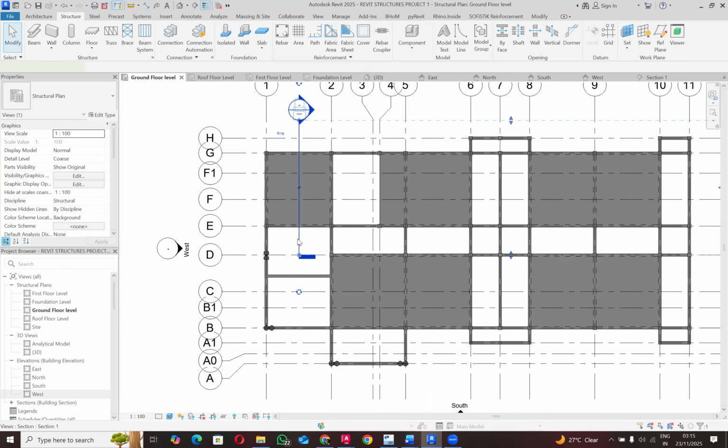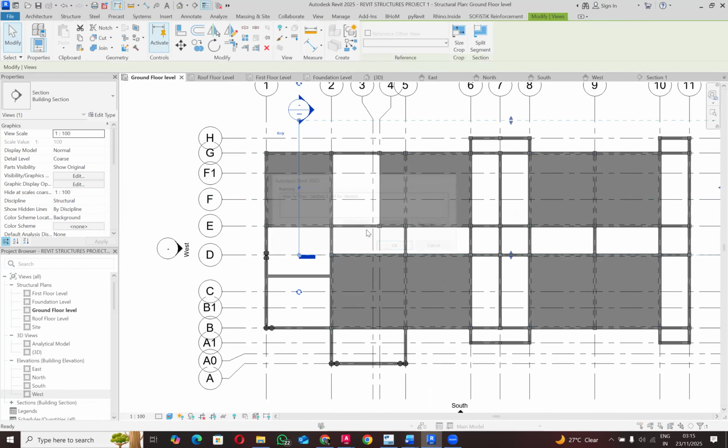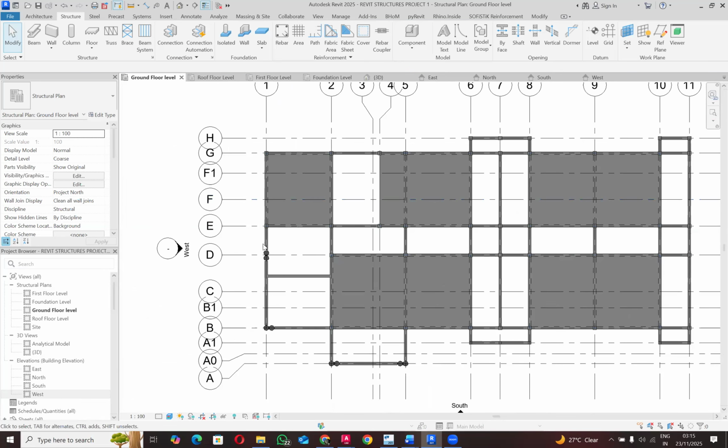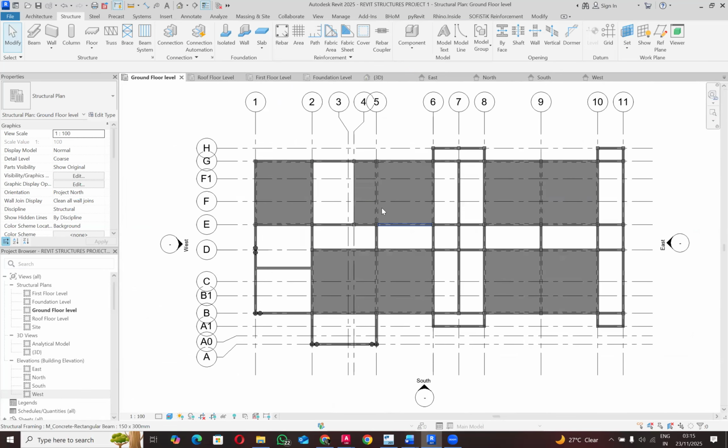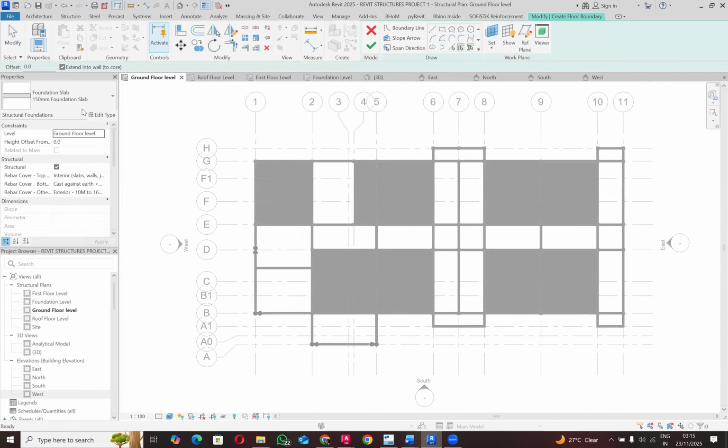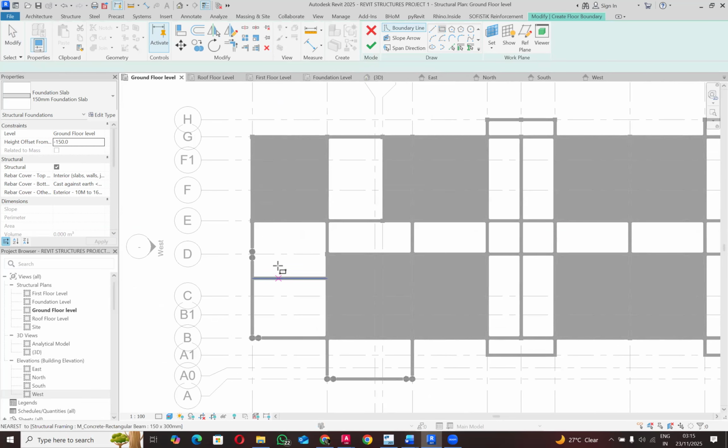Let's delete this section out, right? Yeah, delete this section. Okay. So the next thing I want to do is now model the step down one. So let's select the change, now just 150. So this time let's do minus 150 offset for those slabs, right? So just delete.